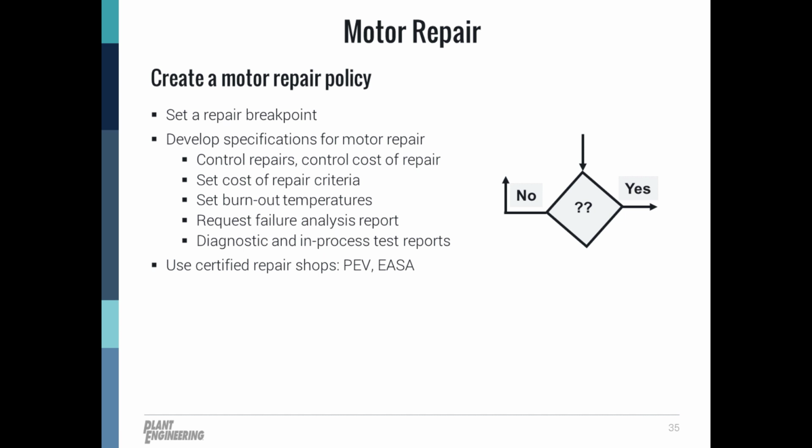The general, straight line specifications like this may not necessarily work for your facility if you have motors that are really old, predating any kind of efficiency regulation. So really old, maybe inefficiently designed. That's where a horsepower breakpoint study can really help you. And that would be tailored specifically to your facility, not just a general example, like what I just mentioned. The breakpoint study will take into account not just repair versus replacement costs, but also the energy savings you'll earn with an energy efficient upgrade.